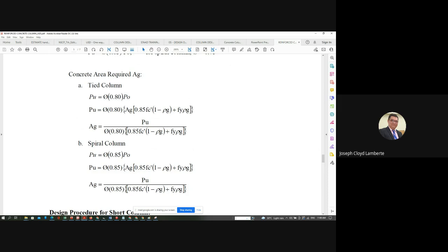If you intend to use only 1% steel ratio, it will give you less steel but a somewhat larger concrete area. If you opt to use the maximum of 8%, then you will have a lot of steel, and the size of your column will be reduced. But the steel is plentiful. So you choose there. However, here in our 6-pack, 6% is enough.